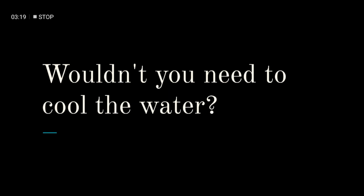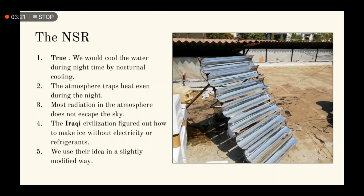Wouldn't we need to cool the water? Yes, I did mention that we would be using cool water, and yes, we would need to cool the water. How are we going to achieve that? By the NSR. The NSR is a night sky reservoir. We use a technique called night sky cooling to cool the water. Basically, we cool the water during night time, and that is done by radiating the heat into the atmosphere. Now, most of the radiation that is emitted from the earth does not escape the earth's atmosphere. Only the ones that lie between 8 and 15 microns of wavelength escape the atmosphere.